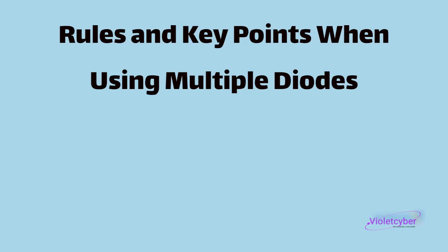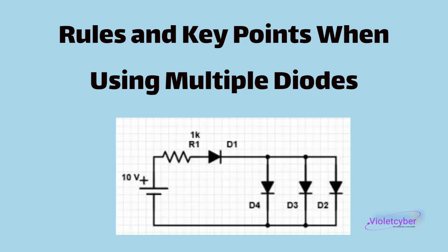Rules and key points when using multiple diodes. And now we want to talk about rules and key points when using multiple diodes. Proper diode selection. The diodes being combined should be compatible in terms of forward bias voltage, current rating, and breakdown voltage. Use of balancing resistor in parallel connections. Balancing resistors are commonly used to ensure even current distribution among diodes in parallel connections.